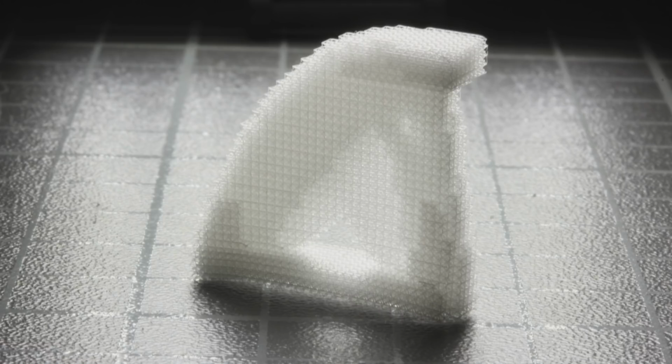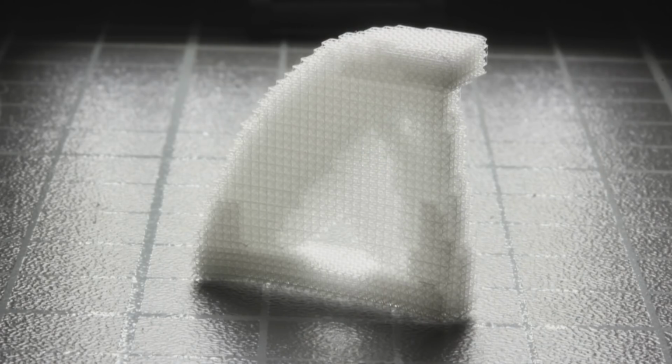And what is important there, and what I think is in fact exciting, is that with one feedstock to a 3D printer, we're able to produce different material behaviors. Because what we gave the algorithm was a different Young's modulus at different locations in the cantilever, and it produced a functional gradient of lattice structures.